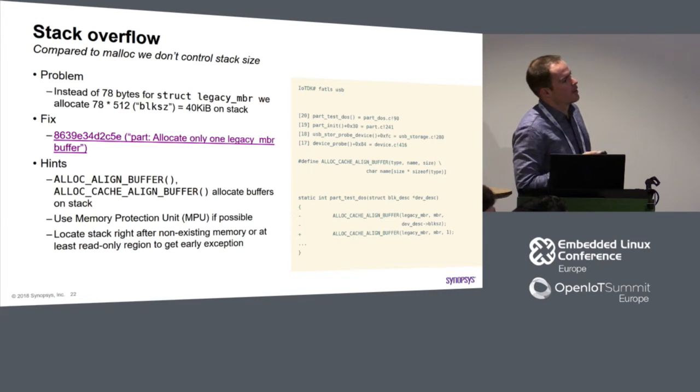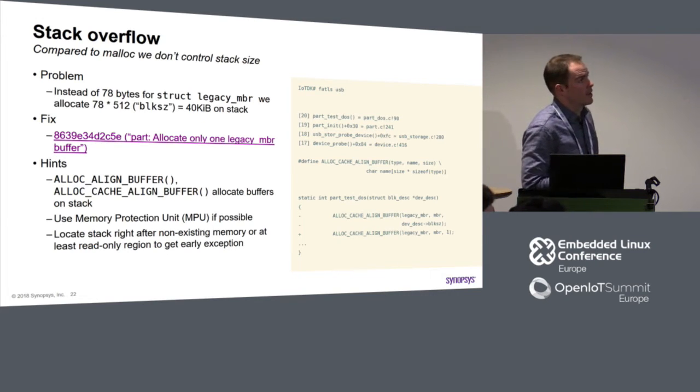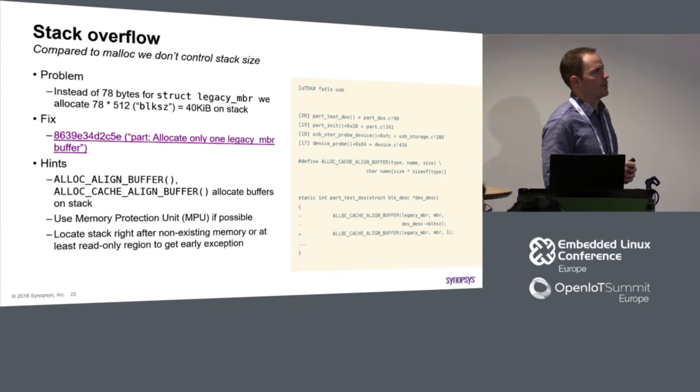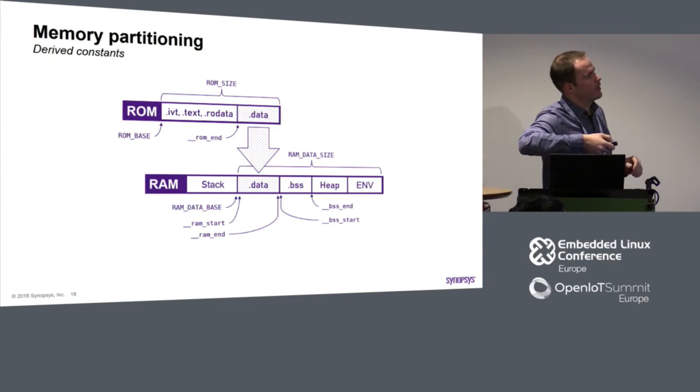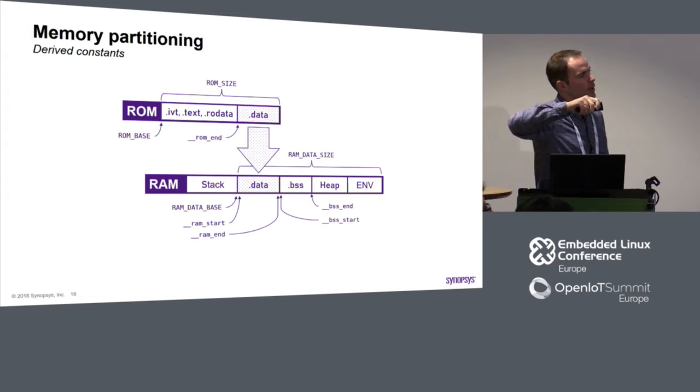And so then I took a look at registers, and what I noticed is that my stack pointer register, which is a separate register, at least on our CPUs, was pointing way outside of our RAM area. And if you return to that slide, you see, it was pointing somewhere here. And that is the beauty of the stack being here, because there is no memory here, and my memory subsystem just returned an exception. If I had put that stack area somewhere here, for example, after data, you may imagine what